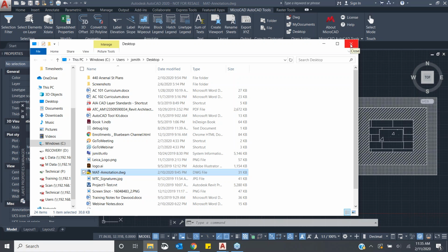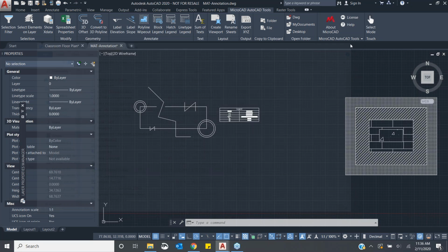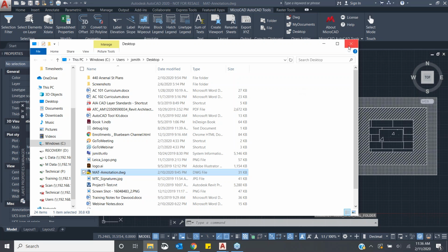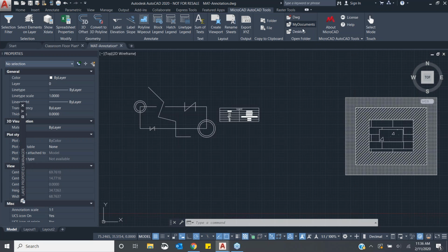I love this option here, because I'm sure many of you have been in this situation. If you've ever opened up a file that was auto-recovered, and you're not 100% sure where that file may end up, because you have your temporary files and all of that on your computer, and sometimes it's hard to identify where AutoCAD saves those for you. This will always find that location for you very quickly if you ever have trouble locating an auto-recovered file. When you're panicked because something crashes, it's so nice to know that you can just very easily click that and get to that location really quickly.